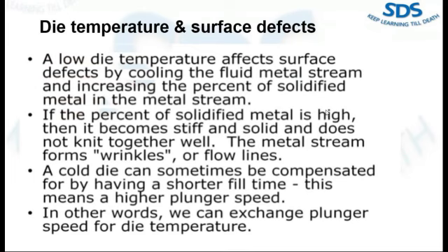If you find your supervisor or operator very busy on the shop floor, yeah, we don't have time, so they are doing only this. They are compensating every hour. There are a lot of parameters I explained in this. So they are adjusting or compensating every hour. Sometimes they are reducing high speed, sometimes increasing high speed, sometimes reducing spray time, sometimes increasing spray time. What are they doing? They are compensating the other parameters only to achieve this filling time.